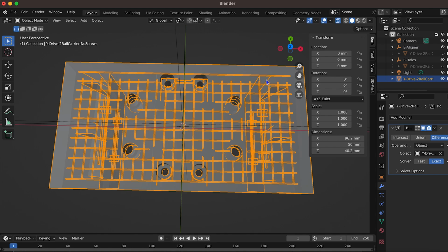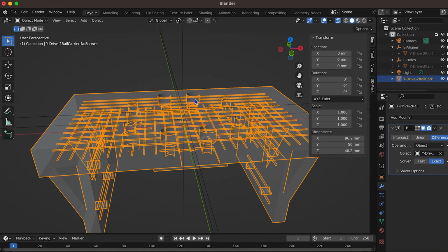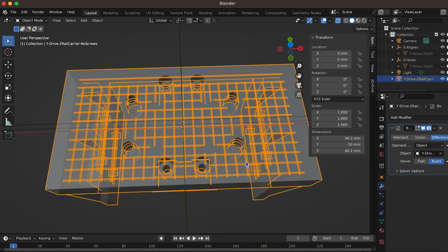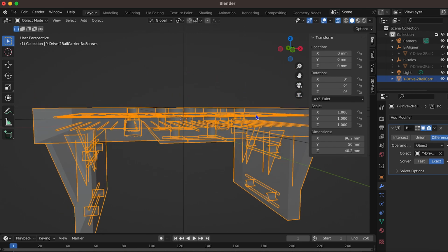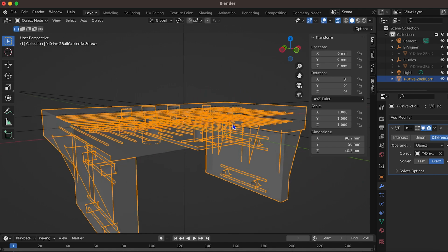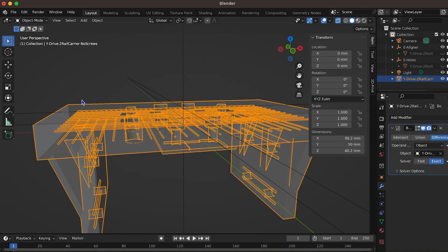Just a little comment. If you wonder what those lines are, these are tubes, so to say. They're cylinders with a diameter of maybe 0.5. And what it does, you see I added 2 layers, one in the Y direction and the other in the X direction. So this is stabilizing because, as you know, the slicer would just infill this, and I want this design very stable, and this is why I added that.